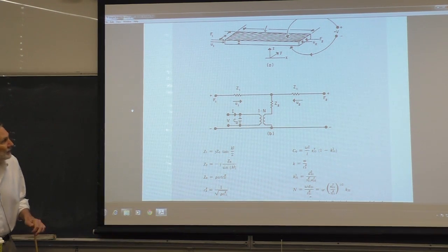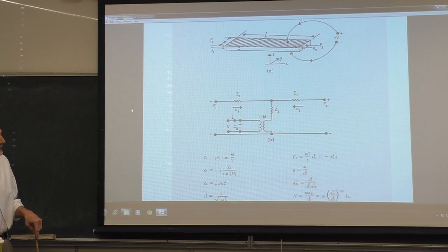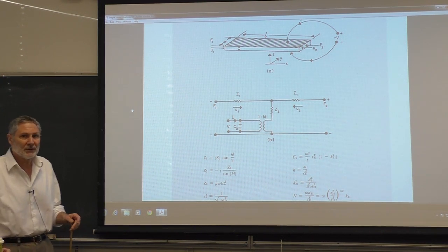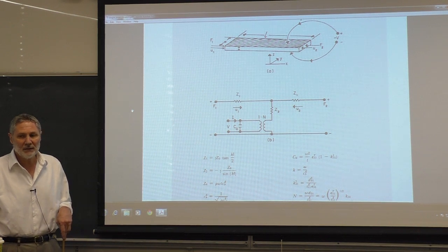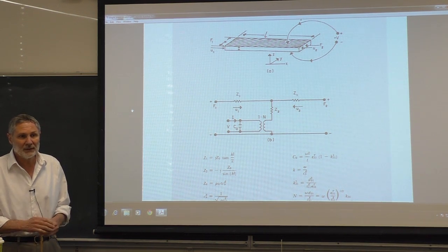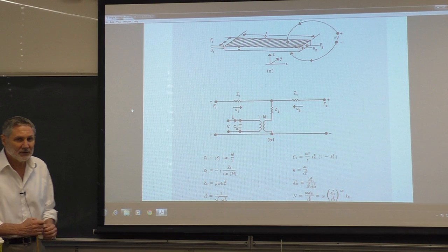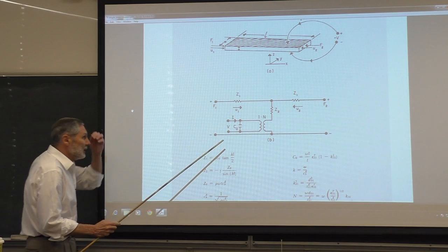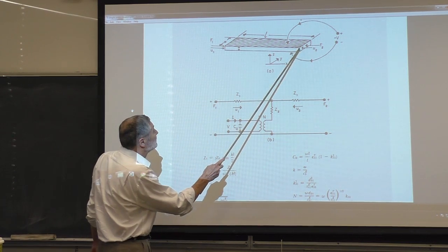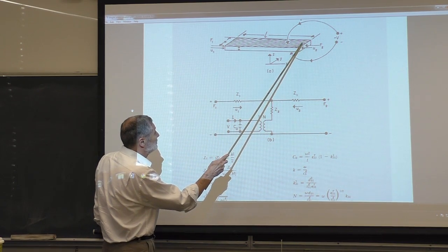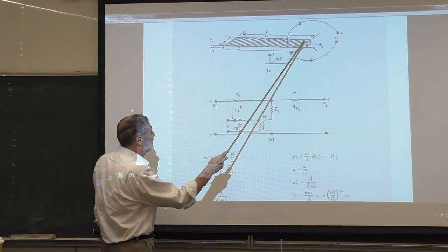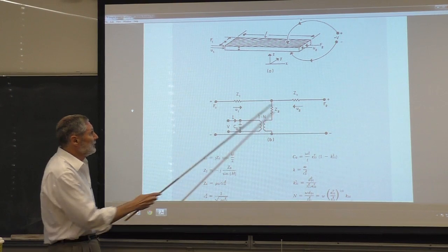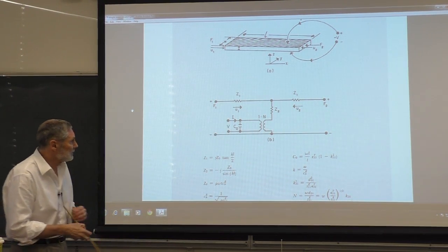So the first thing you want to see about this T network is that we don't have a two-port system anymore. We started off way back in chapter 2 with the canonical transduction theory with these canonical equations. We had two ports. Now, because there are two mechanical inputs or outputs here, we're going to have three ports. So here they are. There's two mechanical and one electrical.